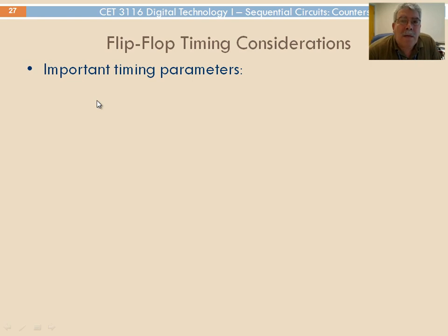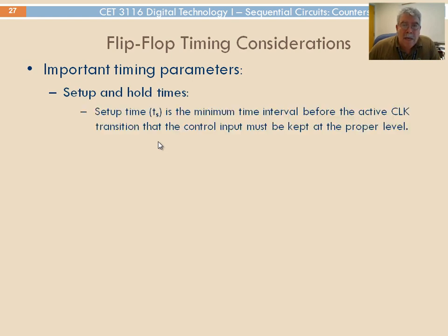Remember when we studied flip-flops, we studied certain timing parameters. You will see that these parameters are very important as the key to designing counters. So one thing is the setup and hold times. If you remember, the setup time is the minimum time that the input value should be stable before the clock comes.